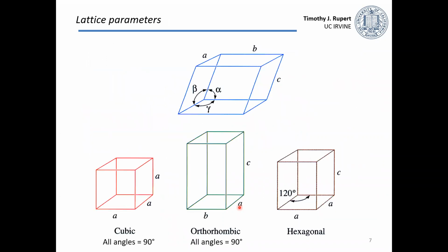Okay, so it's nice that we know those 3 common crystal structures and also that 4th one, which is simple cubic. But not all materials form these types of structures, so we need to relax those limitations. We've only really talked about highly symmetric systems up until now. But in reality, you can have different lengths of the sides of this repeating unit and also different angles inside to describe this box, okay? So cubic is really the simplest case. It's where all the sides have the same length and all of the angles are 90 degrees.